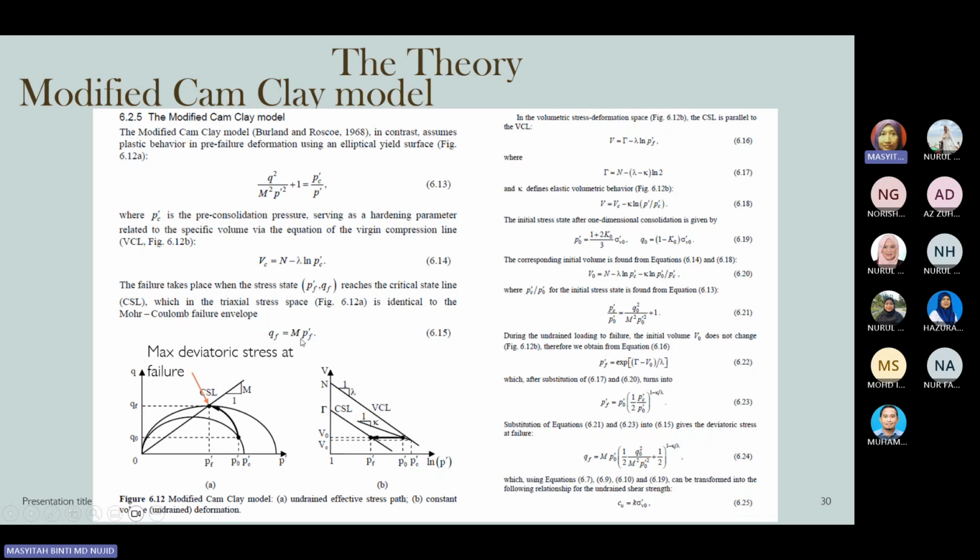So it states that finally, whatever you have from the complex triaxial plotting of the soil behavior when subjected to loads, it can also produce a similar, or what we call a linear, equation that can also be found from the Mohr-Coulomb model. But this is a very good model compared to Mohr-Coulomb because it includes the plastic behavior, or what here we call the hardening parameter.